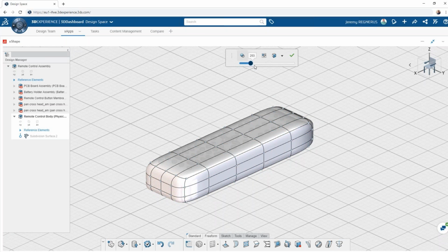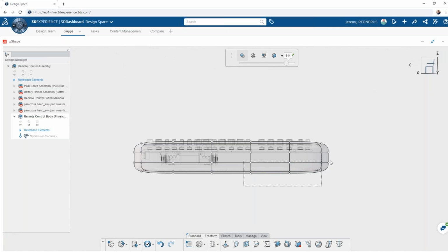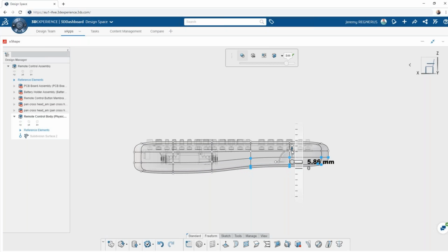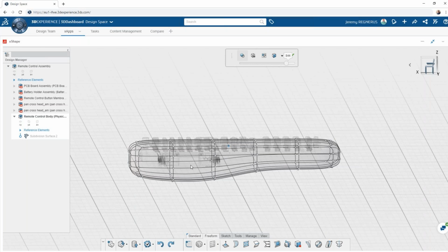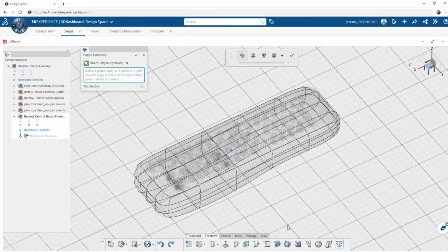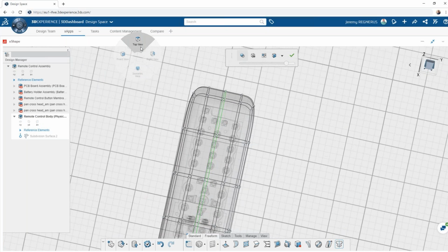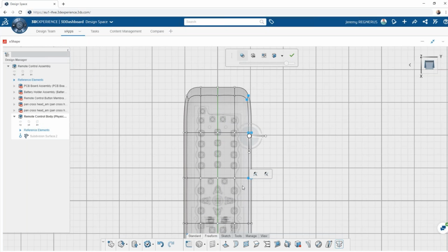At any time, you can select the geometry and start manipulating it freely or with the assistance of on-screen triads also. As you manipulate, you may notice that it retains the curvature continuity across the entire shape, lending itself to a natural and freeform design. You can also maintain symmetry across the overall shape with the design itself. This is crucial when you are creating shapes on geometry that would otherwise be hard or impossible to produce exactly on the opposite side of the part, while also maintaining the curvature continuity throughout the design.